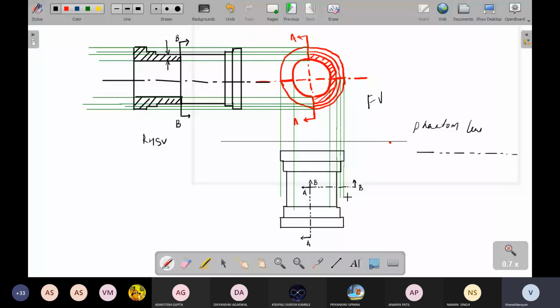That's why we don't show cut, but in this case we show plane of section. So complete information is given in this three view diagram. In the top view, the plane along which the component is cut is shown, and in the front view and the right hand side view, inner details are shown due to the removal of a section.